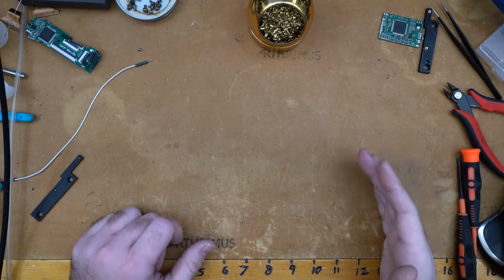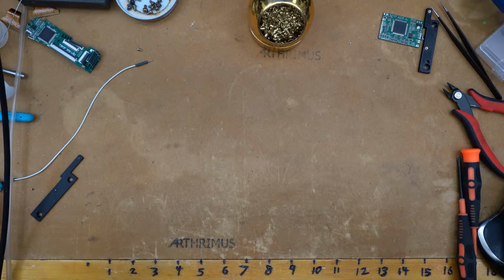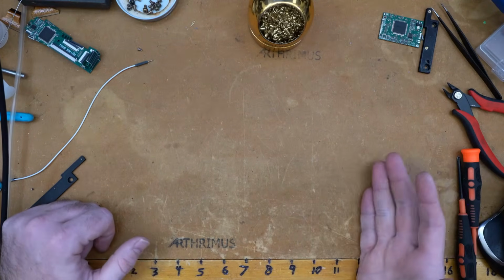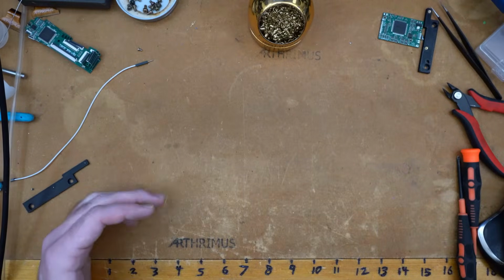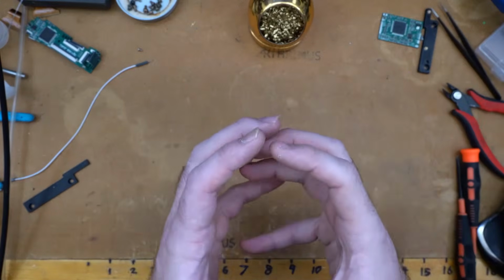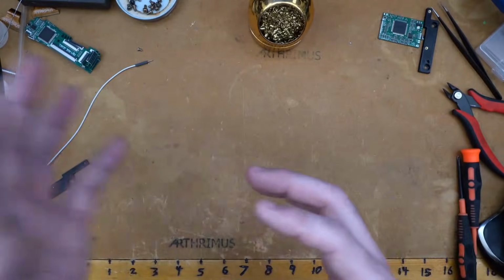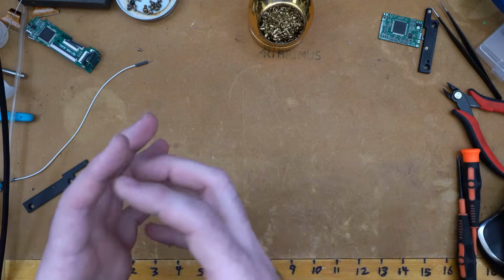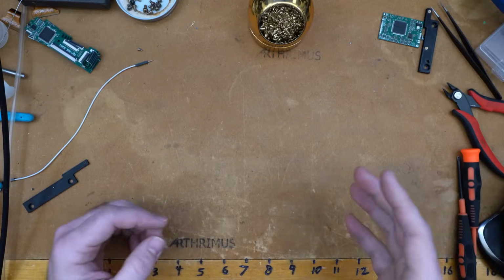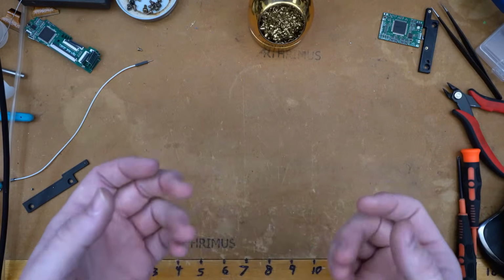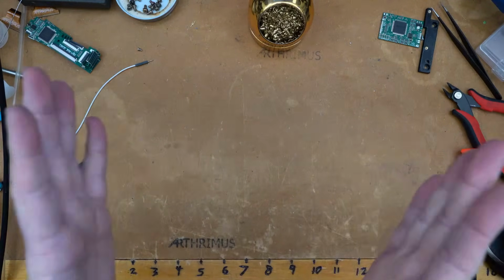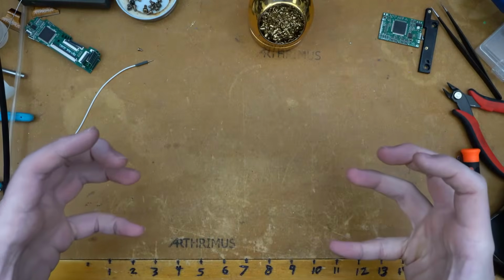They have solved the issue that I talked about on Twitter last time, where the end cap was getting stuck in the non-eject side of the mold, to where the mold would open up and the end cap would pull out with the non-eject side of the mold, and that meant that they couldn't eject it out of there because there's no ejector pins on that side. So they fixed it by creating these extra, basically, pillars that go up into the eject side of the mold to create more resistance to hold that piece in the correct side of the mold.